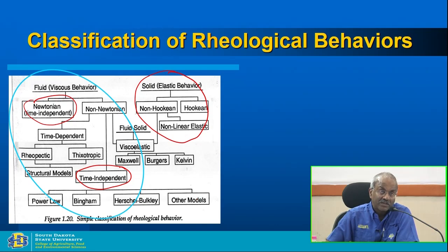You will be surprised when we talk about those things, saying, oh, there are different types of fluids. You probably expect, okay, give me a viscosity value, my life is good, right? I need one number, then I can live with that. It's not that easy. If you really think of viscosity as one number, you are making a big mistake, because unless the fluid is Newtonian, it will not have only one viscosity number.